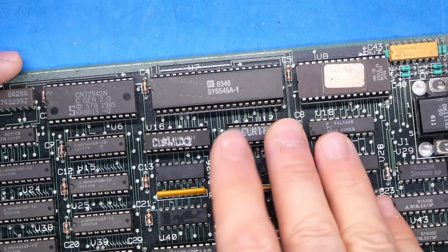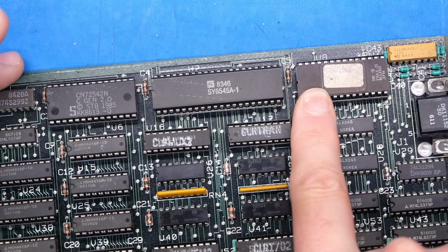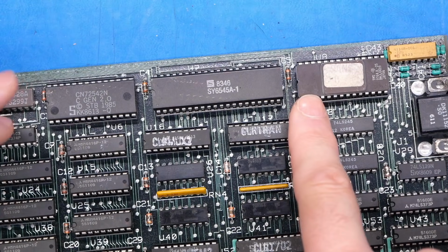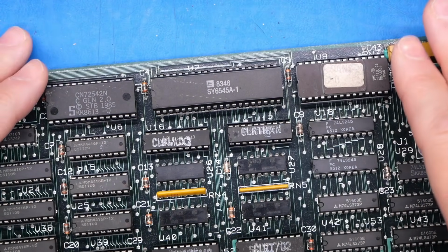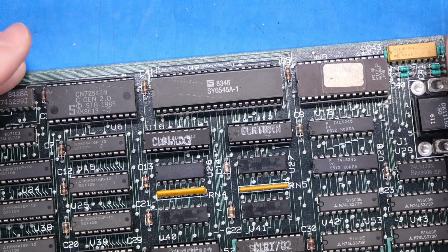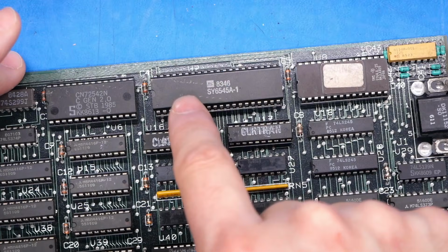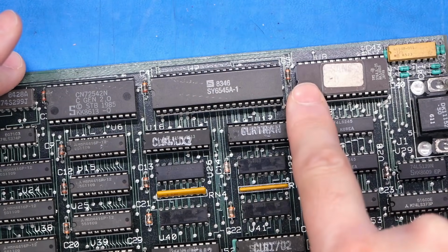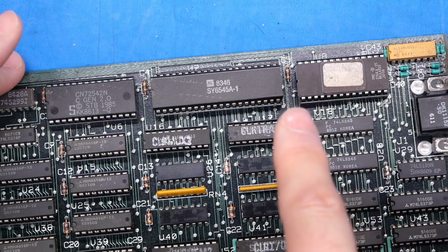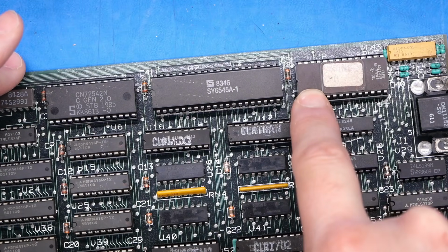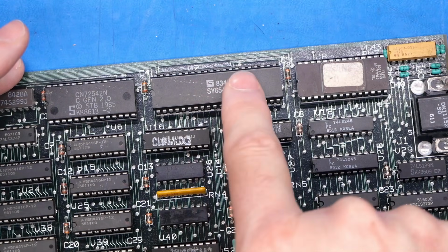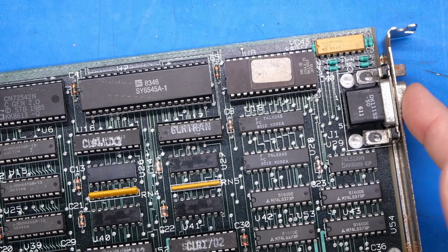And that's exactly what I think is happening with this ROM chip right here. This is not a normal BIOS ROM like an EGA or VGA card has. This thing just uses the standard CGA mode on the BIOS. But I think what happens is as the writes come in to go to the CRTC, they are translated by this from the standard CGA or MDA values into values that are going to end up giving the correct scan rate out of the video output here.